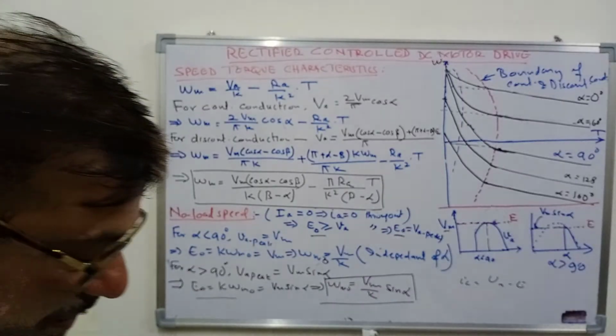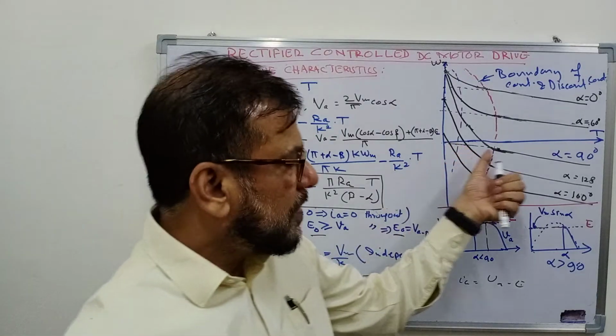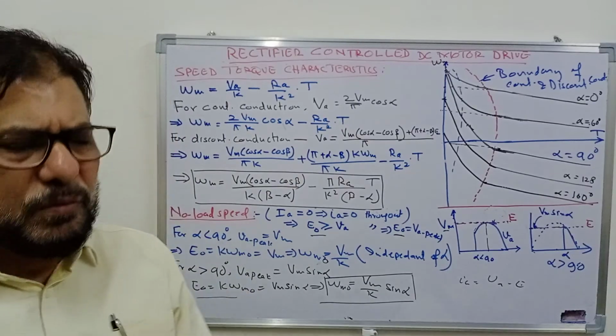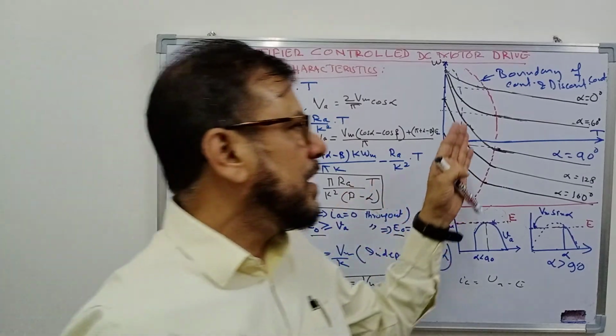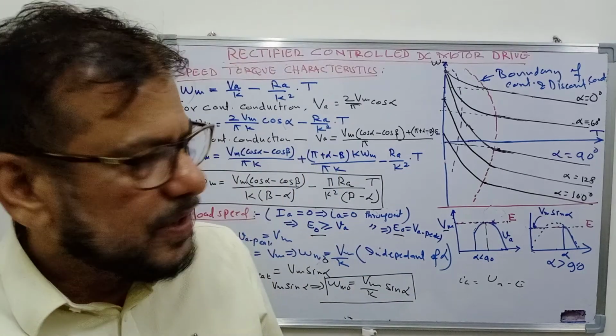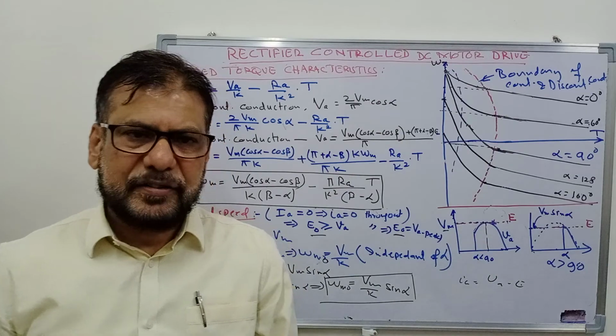So if inductance is high, then the range of torque for which the characteristic is discontinuous may be very limited, and in most cases the characteristic will be linear. So this non-linearity is avoided in this way.